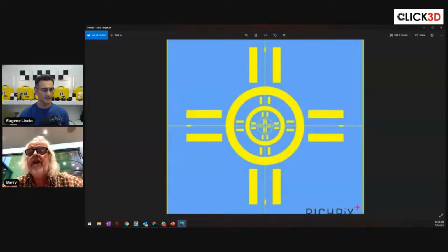All you really need to be able to do is measure where the center of that is. So it's only the center that you're really interested in and getting the crosshairs lined up. But I found this is the one I've used. I've used this design for 20 years, and although there are other targets, and you have to use these in some of the auto recognition ones, I can see some behind your head. I'm not a big fan of the checker targets because I'm an old school person. I like to manually pick my points because I trust it. Just call me old fashioned, but to me, this is just one. There are plenty of others out there, but I shared this because it's been a trusted tool that I've used for many years.